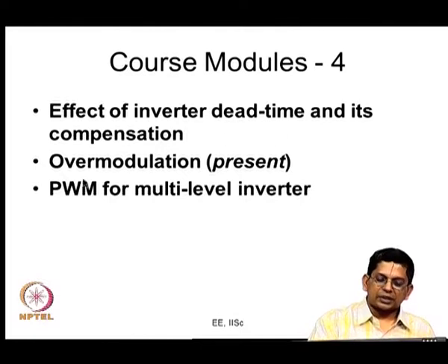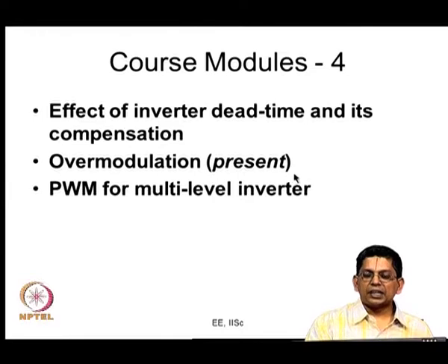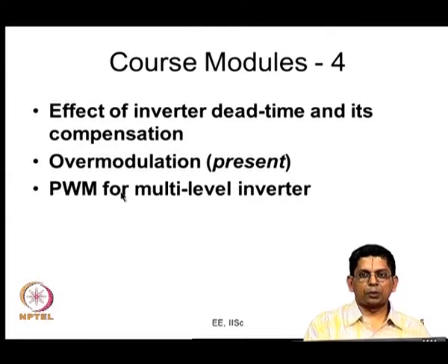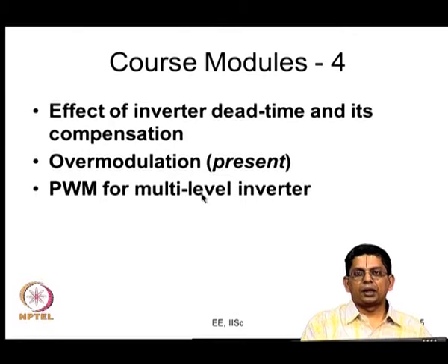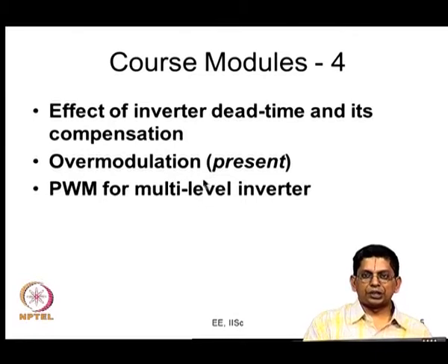Now, we are going to look at something where the ideal fundamental voltage itself is not proportional to your voltage reference. We are going to go into the nonlinear region of operation of PWM rectifiers, where the inverter voltage may not be proportional to the reference. So, why do you have to do that?